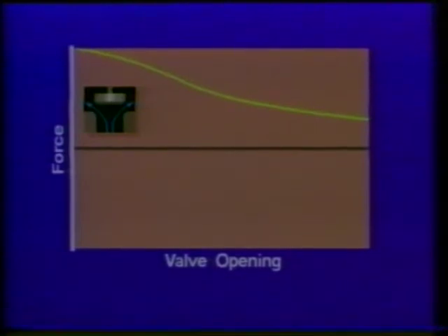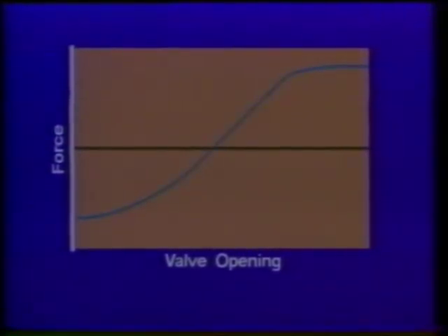As you can see, the force varies with the amount of flow through the valve. With the same valve installed so that flow tends to close the valve, the dynamic forces acting on the plug are considerably different. Again, the direction of flow through the valve is important. Of course, the shape of these curves is also affected by valve design. For example, this curve represents the dynamic forces on the plug in a double-ported valve. Clearly, it affects the complexity of actuator sizing.